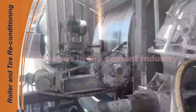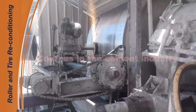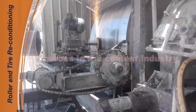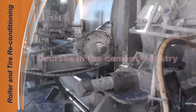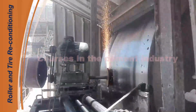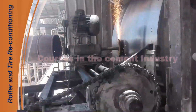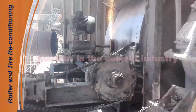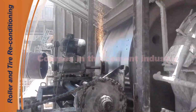From the site, I present to you this video, which shows the grinding process for supporting rollers. I have some notes to share. 1. Rollers are reconditioned while the kiln is in operation. 2. Also machining a kiln tire while the kiln is in operation. 3. This roller is being resurfaced by grinding rather than machining. 4. Also resurfacing a tire by grinding.